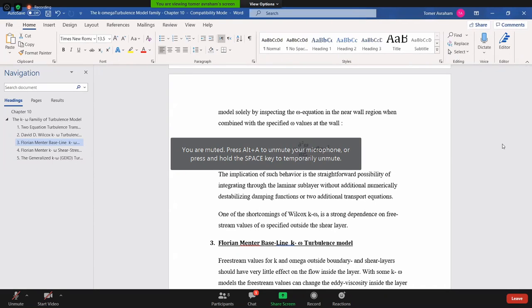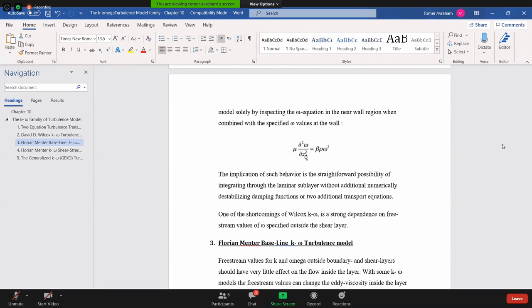But because you don't have this kind of computer resources, you actually put a low-pass filter on the equations, okay? So then you have resolved scales until you get to some level where there is a subgrid scale, which is a model also.